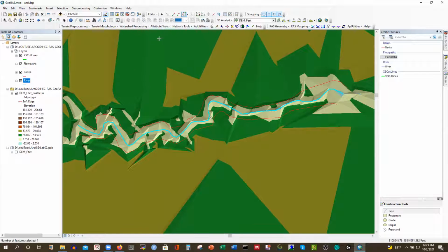Then I have to draw 2 different lines. To do that, don't activate trace again. Click on that straight segment, and then follow another line that will be a little offset from the left bank to create that flow path. So for flow path, we'll have 3 different lines.